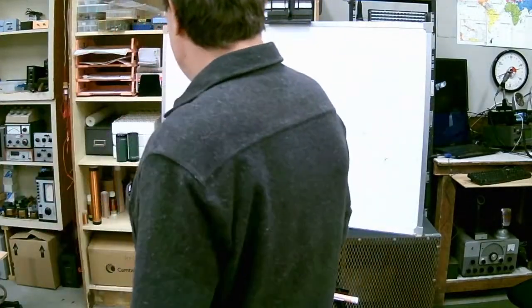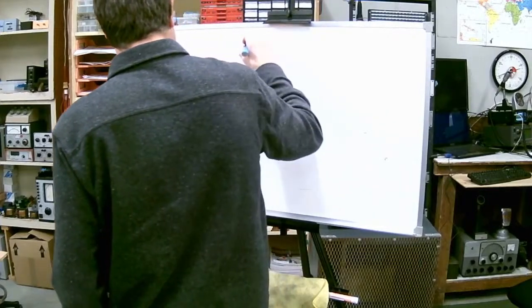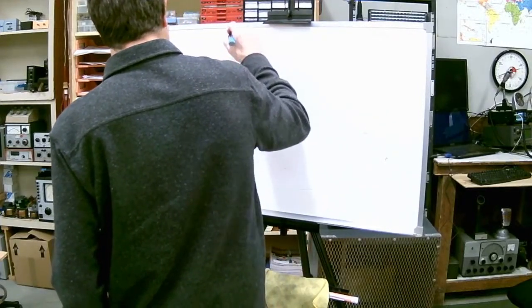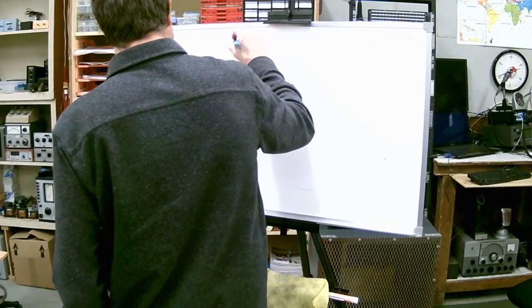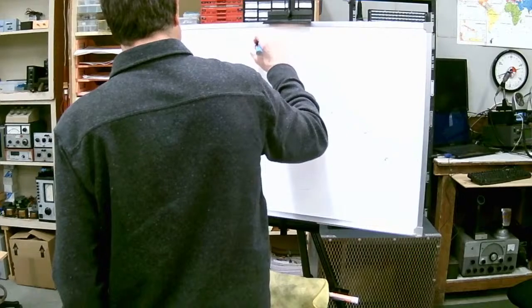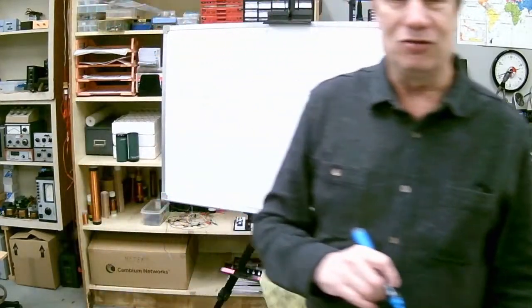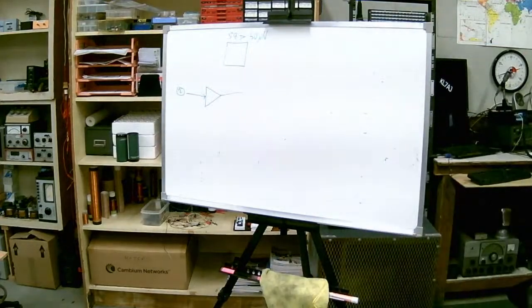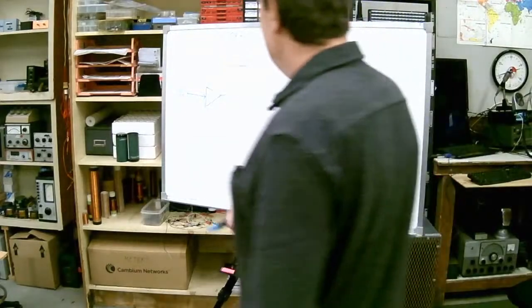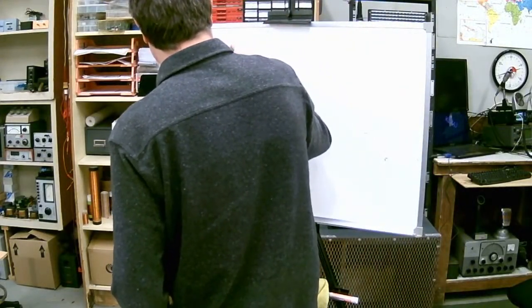So a typical receiver there, a strong signal is considered to be what we call an S9 signal, and that's equivalent to 50 microvolts across the antenna terminals. Now, that's not chiseled in granite, but it's a pretty long-standing standard for communications receivers.